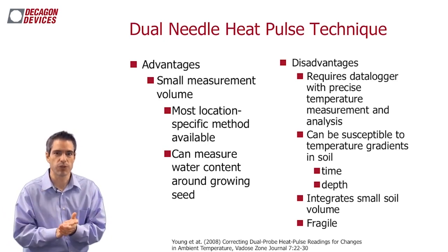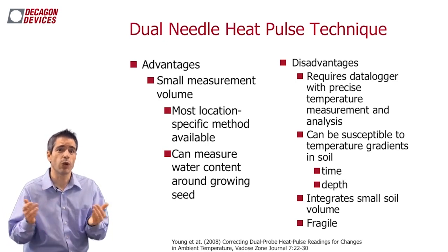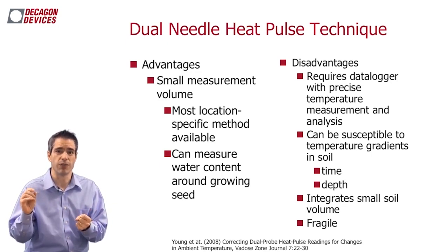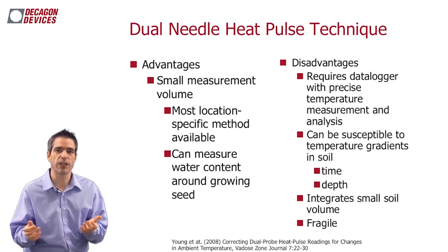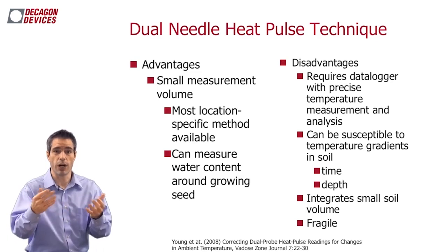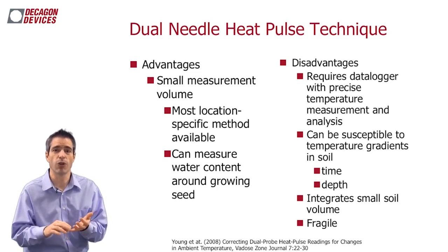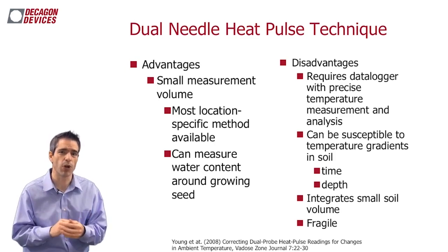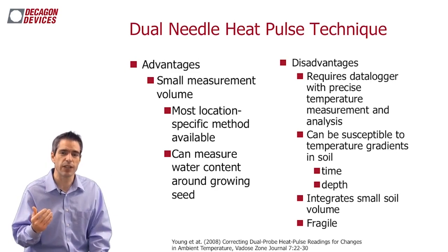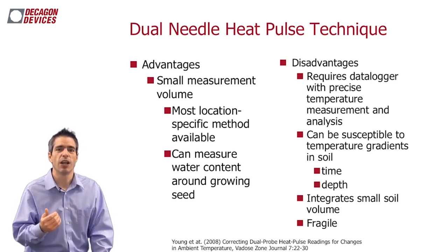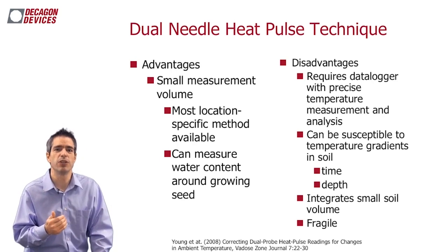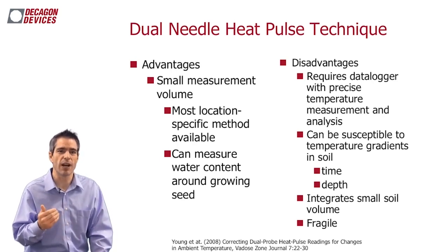And that's absolutely true. But there are some cases where we'd really like to know the soil moisture in very small volumes. Think of a desert crust where we're trying to figure out whether or not there's water available or water present in that crust that might be useful for growth of some kind of organisms. Well, these would be the only probe that you could use to measure that desert crust. And that's been done in the paper that I note there at the bottom of the slide.